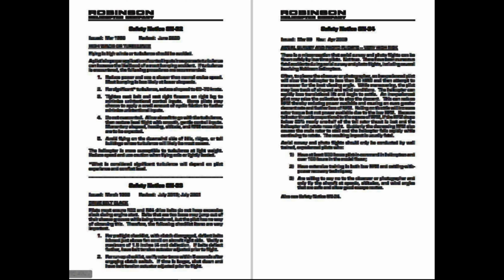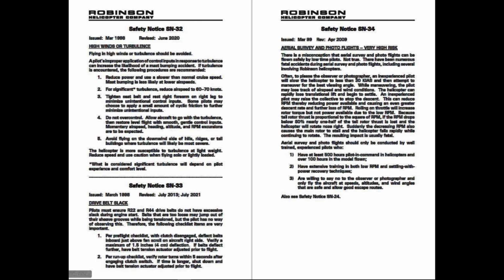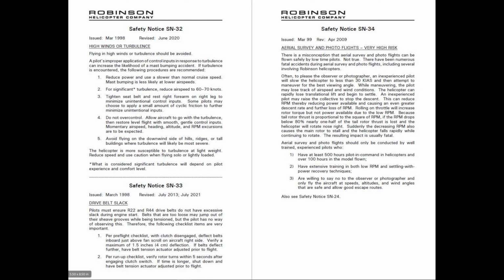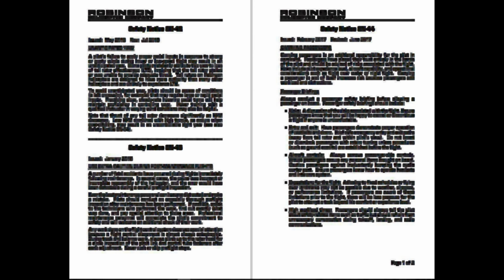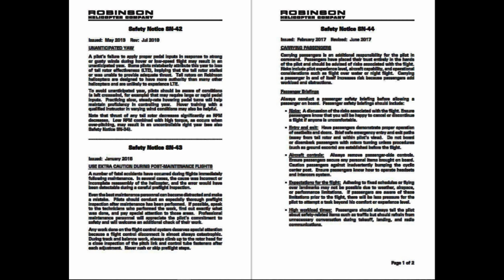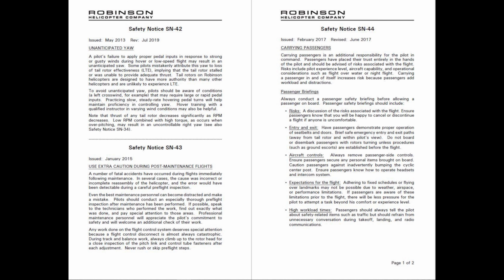If the RPM decreases to 80%, how much power is lost from the tail rotor? Nearly 1/2 of the tail rotor thrust. What may cause unanticipated yaw? A left crosswind.